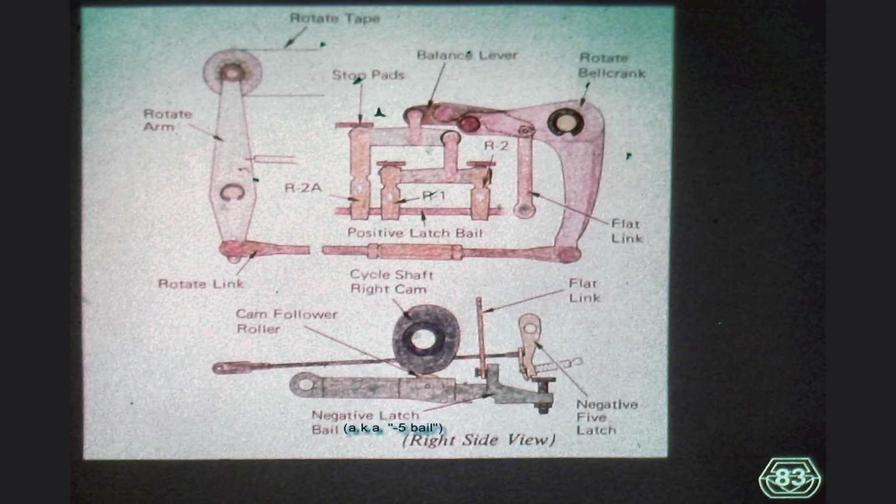Now let us hypothetically filter out the archway and R2 selector latches and pull down only the R1 selector latch. Because the link connecting the blue lever to the green lever is located 1/3 of the lever's length away from the R2 latch, above which the stop pad functions as the pivot point for this operation, the total motion transferred to the blue lever is only 1/3 of the vertical input motion. That means at the balance lever, we obtain only 1/3 of the 3/5 maximum motion possible at the right end of the blue lever. And 1/3 of 3/5 is 1/5.